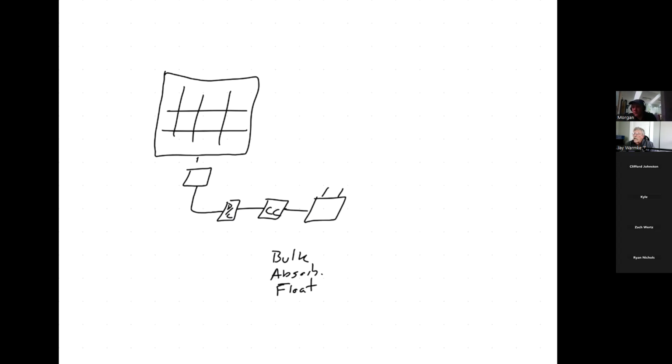And I just noticed in the chat, Zach had asked, what does the inverter do when you lose a leg from the grid? All right, so I'm assuming you're saying, okay, we've got single phase electricity. It could be three phase, I guess. And you've lost one of line 1 or line 2. So now you're hooking up to 120. It's going to shut off. I mean, it needs to see 240 volts. If it's not seeing a grid as it's supposed to see it, it's just going to shut off.